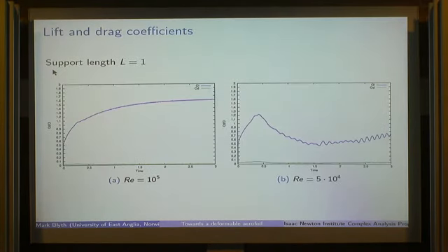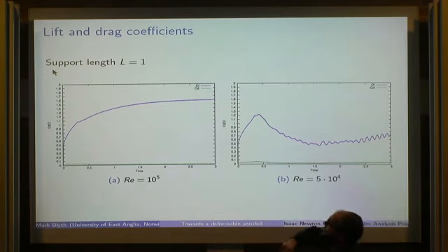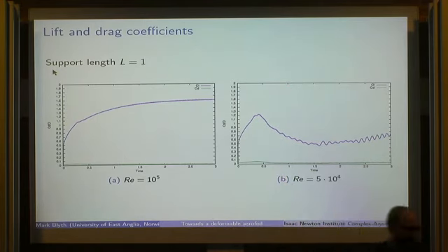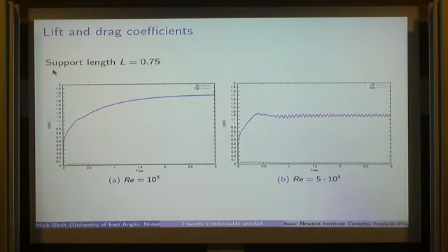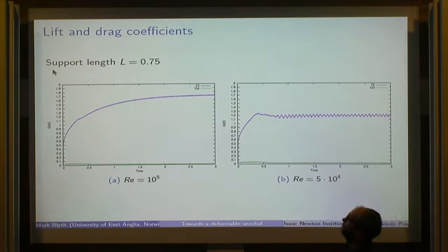And just quickly to end up, corresponding to those two movies I showed you is the lift coefficient again for the 10 to the 5 case. It appears to be asymptoting towards a value which is closer to 2 than before, so it's more successful in mimicking a potential flow. And one can play with the length of that strut. It doesn't have to be fixed. We can do calculations with different lengths. And what's happened now is that the asymptote has moved up closer to 2 again.